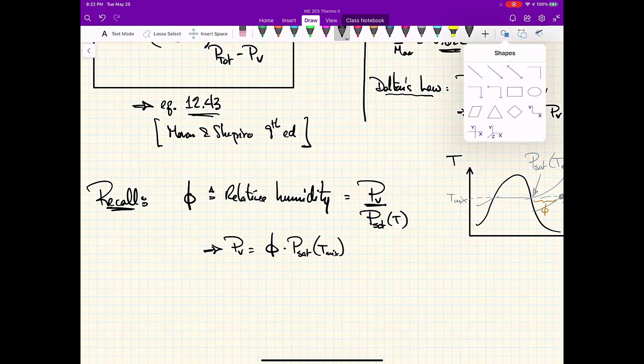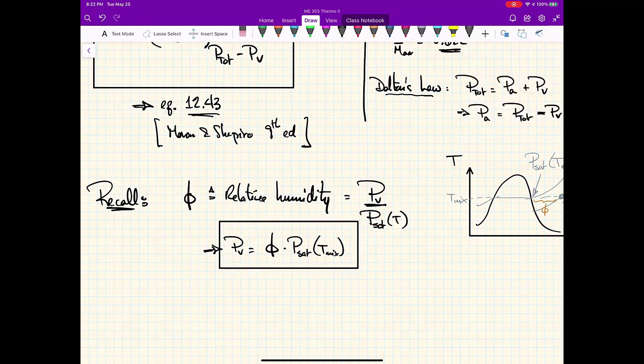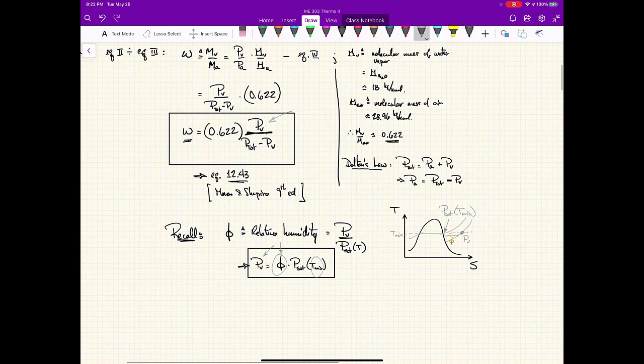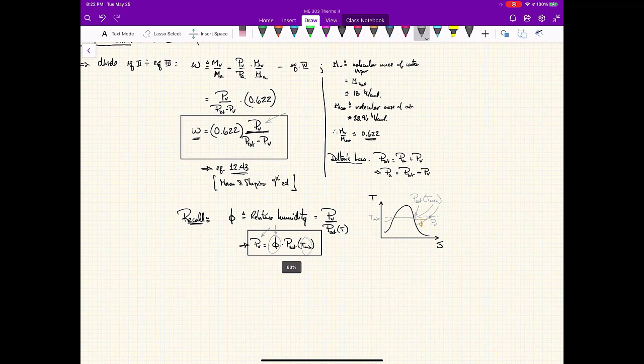Okay, voila. So now you see that I got the humidity ratio as a function of the vapor pressure, and the vapor pressure as a function of the relative humidity. So very often we have the relative humidity given and the temperature of the mixture given, and you can see how I can weave myself back up there and find the relative humidity immediately as a result of that. That's the key lesson here that we've got. How does this all work?